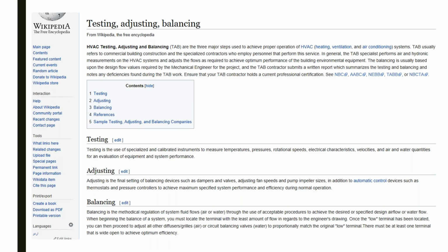It's both, because I do know what you're talking about. Sometimes they want to recategorize the building. And so the TAB report will go over every piece of equipment. It'll list everything that they read and measure and adjust. They will write it down, and so they'll locate it just in case somebody added something that wasn't on the drawing. We run into that a lot, where somebody has made a modification that they did not document, and so 20 years after the building's built, here's this new piece of equipment that nobody knew anything about.